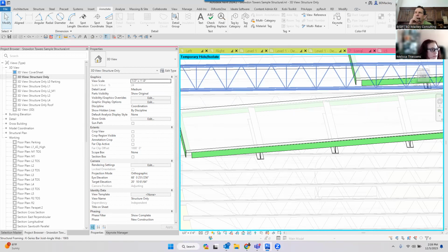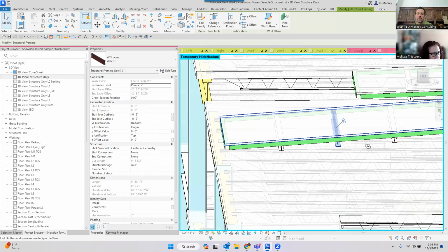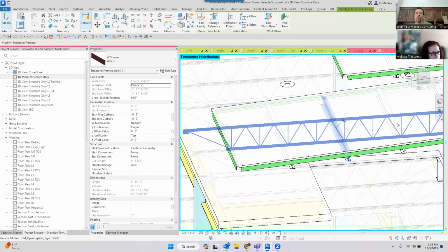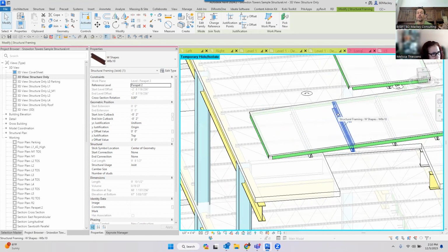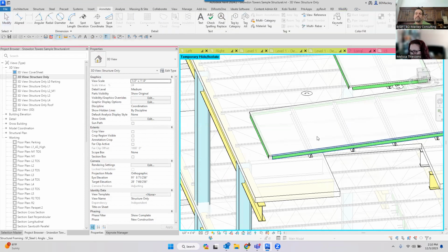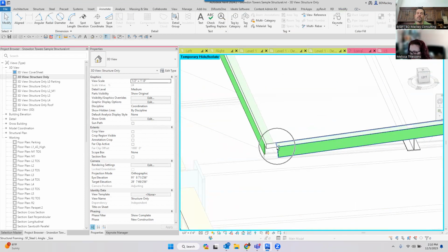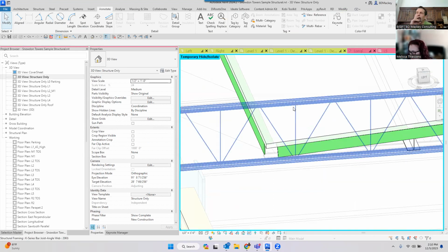And Mark followed up, saying, oh, so what if you have both? Like if some of these needed to be rotated perpendicular and some not, yeah, I'd be doing a beam system with 12-foot spacing and then just changing it up. I might model it twice. So I might do half of them where they're associated to the work plane and then the other half where they're associated to the elements. But I'd still be using a beam system regardless. I would just set the work plane for that beam system to be the underneath side of the deck.